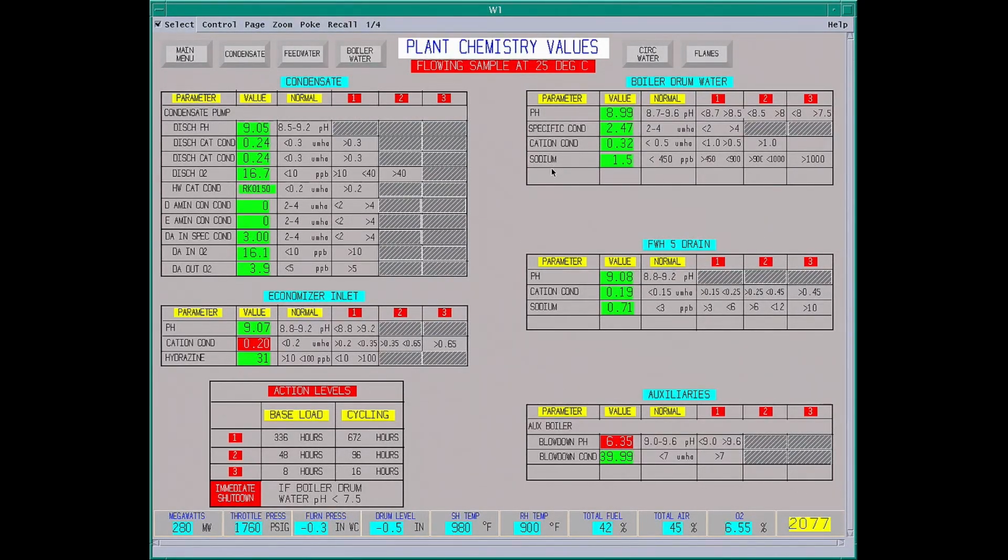They can cause intergranular corrosion, stress cracking, and turbine blading problems along with the sodium. So those 3 items have to be very, very low in the water. You can have problems in your turbine blading in the future. Also at higher pressures and temperatures, they're a lot more volatile. They will carry over. Silica is another big one that at higher temperatures and pressures can cause plating on your turbine blading, lowering efficiency as it builds up deposits on the blades.